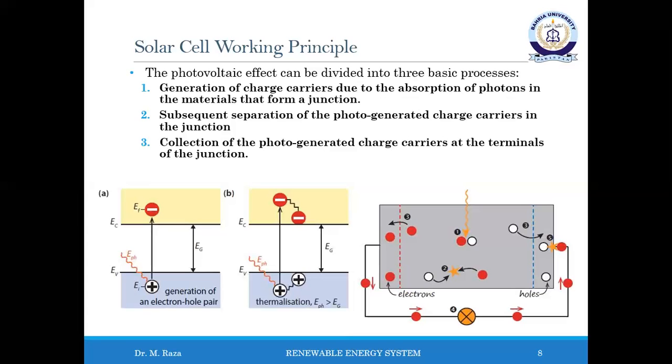The radiative energy of the photon is converted to the chemical energy of the electron-hole pair. The maximum conversion efficiency from radiative energy to chemical energy is limited by thermodynamics. This thermodynamic limit lies between 67% for non-concentrated sunlight and 86% for fully concentrated sunlight.